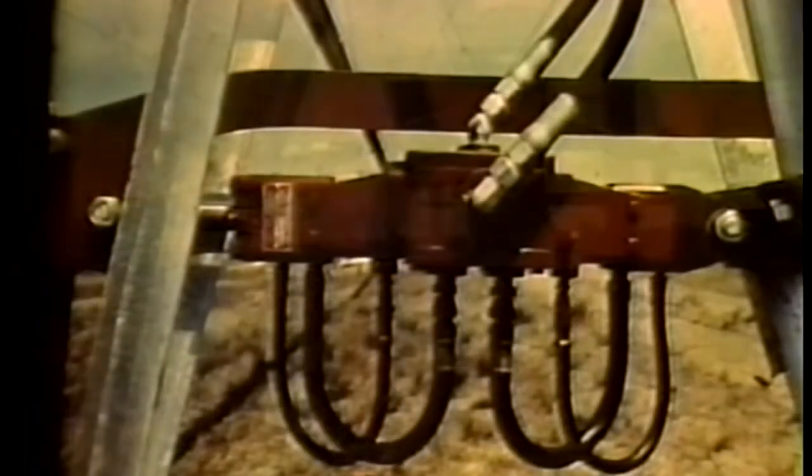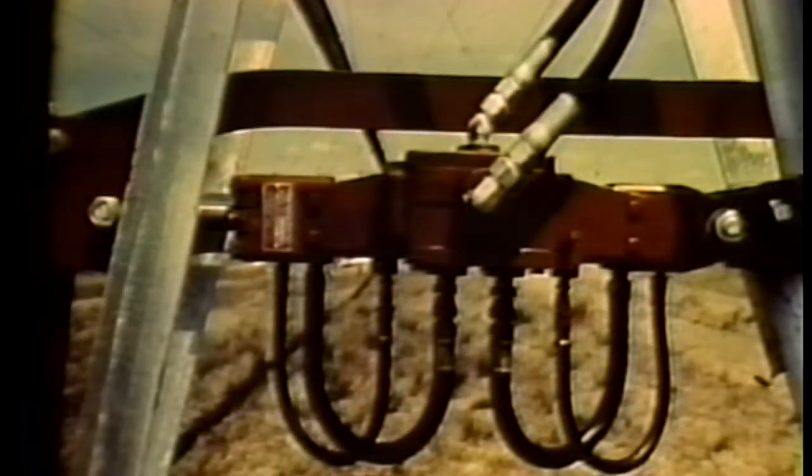Oil hydraulic drives use a hydraulic motor which is attached directly to the wheels. Power is usually supplied from an auxiliary hydraulic pump. The lateral is kept in alignment by a system of cables that extends the full length of the lateral. When one tower gets ahead or behind, a cable tightens. This opens or closes the proper valves to slow the drive mechanism or to speed it up, whichever is needed.